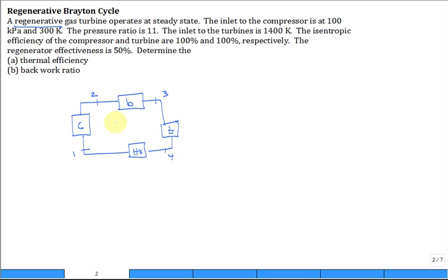And then what they notice is the temperature at 4 is quite high. And all you're doing is throwing that out, Q out. So what the goal would be is to say, well, why don't I try to use some of this high temperature exhaust gases instead of just disposing it to the atmosphere?